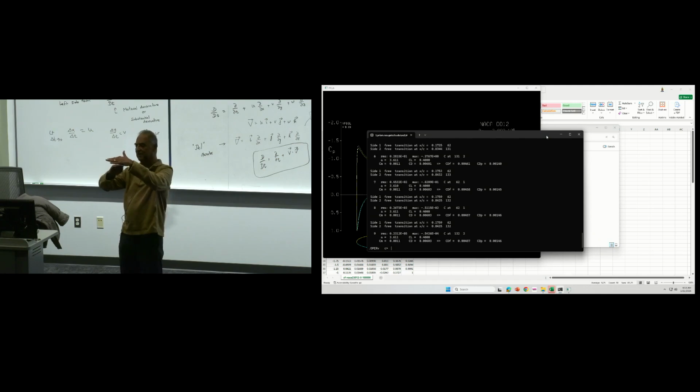What happens is the boundary layer is growing, and it displaces the flow. The streamlines want to move away from the body. One way of acknowledging the presence of the boundary layer is to put in a vertical velocity. So in some viscous-inviscid coupling, they put in the vertical velocity. It keeps changing.